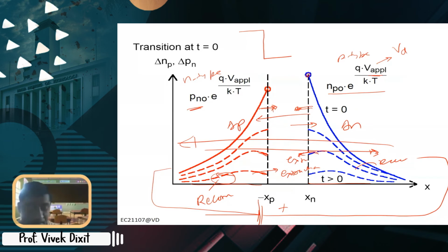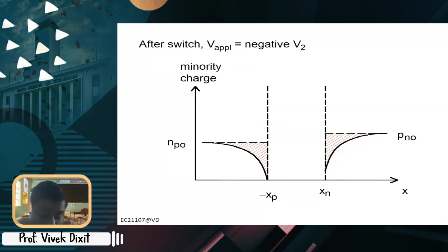Is it okay? Now after it reaches zero, then during a negative voltage, these carriers are further extracted, right? So initially we had a concentration like this, then it changes like this, and like this, and then up to here is storage time, and this is recovery time. And similarly on the N side and P side, both sides actually the same thing happens.